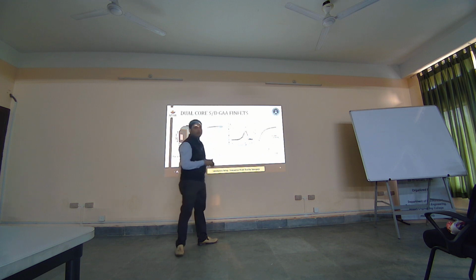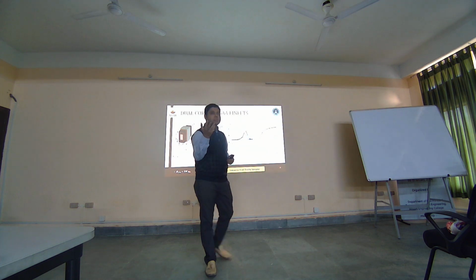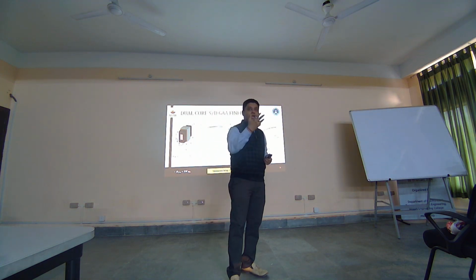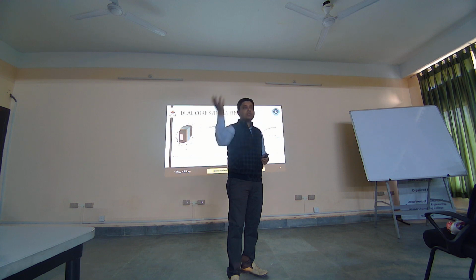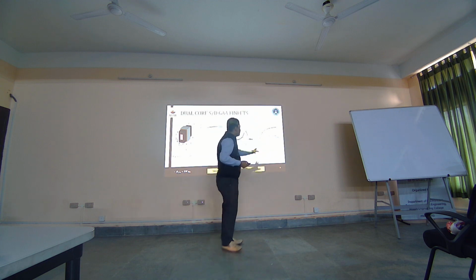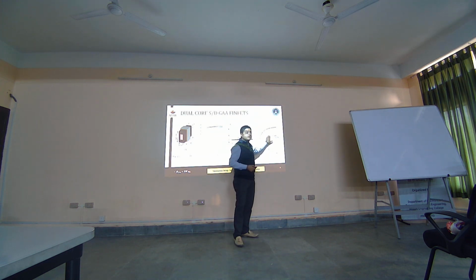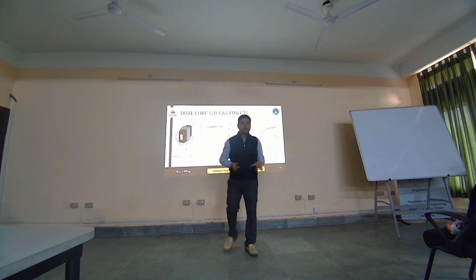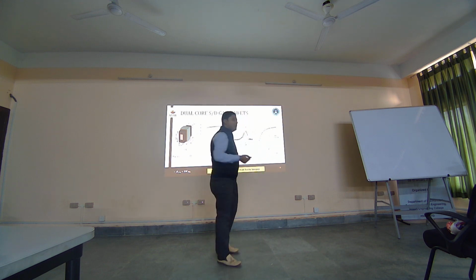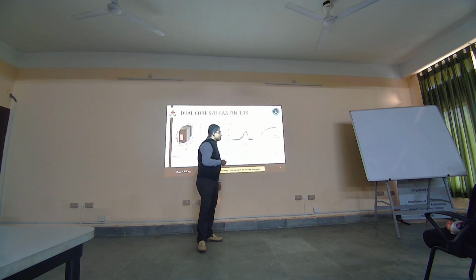So when you get a device which you are going to calibrate, you take the device and create the exact device in your simulation platform, and then you tweak the models so that you get a match between your experimental data and simulated. Once this is fixed, you proceed with whatever constants you have kept for those models, and then you apply them in your simulation.